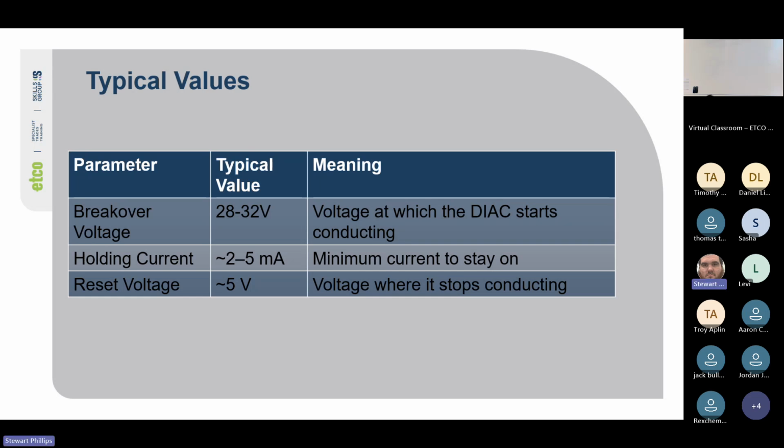Yeah, so that variable resistor is doing the same thing as the rheostat, but in reverse. Does that make sense? So instead of increasing the amount of time the AC waveform or the power is on, we're decreasing the amount of time that the diac is conducting, and therefore limiting the amount of the AC waveform that is going through.